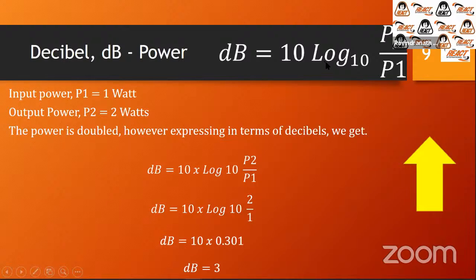It will also have natural logs, which is ln, but you are looking at log, and that usually means log to the base 10. So if you're using a calculator, you're looking for the button that says log. This is the formula for calculating the decibel between one power and the other. So dB is equal to 10 multiplied by the log of power 2 over power 1. We have to calculate power 2 over power 1 first, take the log of it, and then multiply it by 10. You could think of it that way.